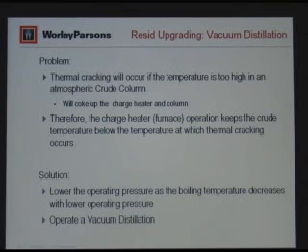So in order to stay within that temperature limit, the other thing you can adjust is the operating pressure. And this is what we do with a vacuum column. Because as you know, as you lower the operating pressure, the boiling temperature decreases. All right?